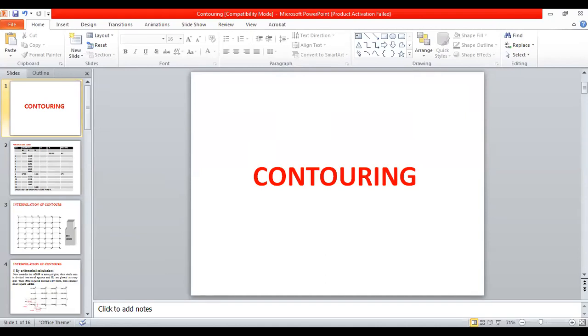You will put the level tube like this. What is the principle of the level tube? There is water inside the level tube. Water is always at the same level. So inside, water is filled. For example, this blue color represents the water inside the level tube. So the water level is at the same horizontal plane. From this we can find that this particular sill level is at the same level. If there is any error in the sill level, then we will immediately come to know what the error is.